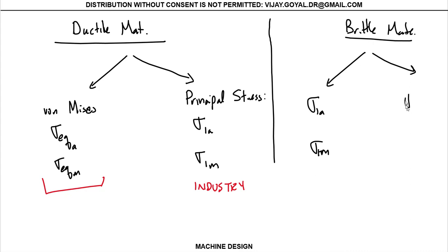The other way you could do it is to find your effective, if you remember your Mohr circle approach, sigma effective alternate and sigma effective mean, okay? You could do either method, but in this course, we recommend you use this method, and this is what we typically do in the industry. And then for your homework and your assignment, you're actually going to compare this solution with this solution. We will do an example for that to better understand how this goes.